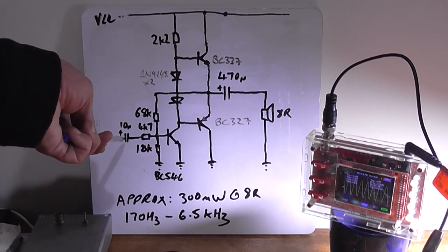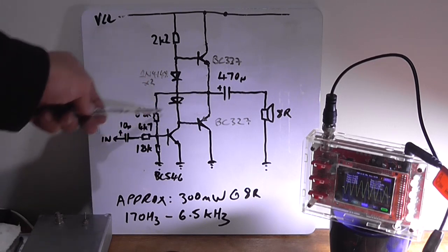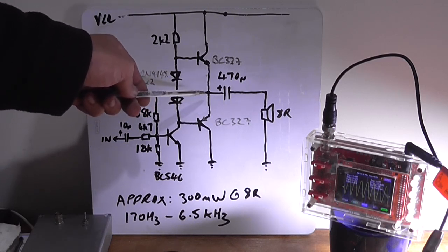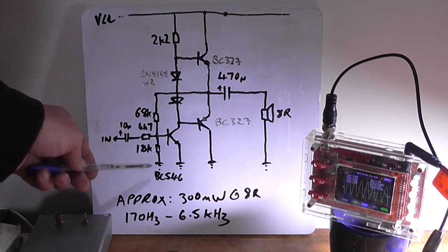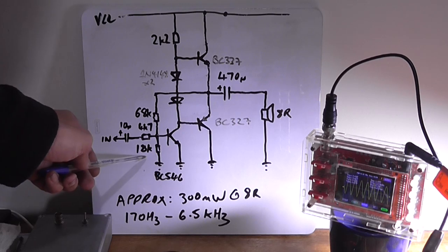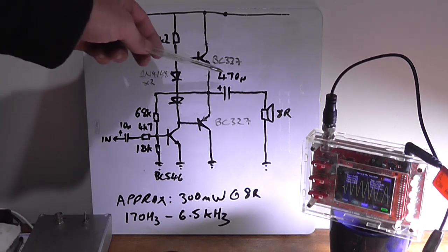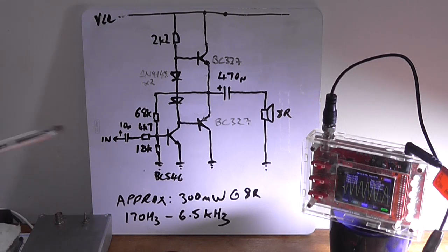Okay, this has remained the same, 10 microfarad, 4K7. The base biasing resistor is a 68K, which comes off the output, so it's getting its DC biasing via the output plus AC biasing to control its gain. You've got an 18K ground reference resistor now here on the first transistor, and that's about the only changes I've made. And of course the output capacitor was increased to 470 microfarad, so I put it as 470 microfarad on the schematic here, so it's clearer as to my tests are valid, so to speak.